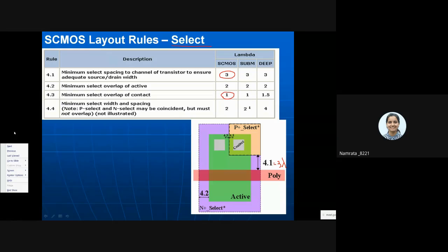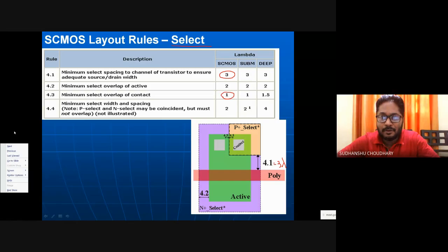In PCB designing, usually we use software wherein they already have the rules, and then we do a DRC check and other things by which we verify. Do we have any software which already has some rules? The same thing exists here also. You will perform a design rule check here also. The rules are already there. You have to select those rules from the foundry, whatever foundry you are considering. You select their rules, start drawing the layout, and then perform a DRC, or design rule check. If there are errors, you have to clear those errors. All those things which you used to do in PCB, here also you will do the same thing.